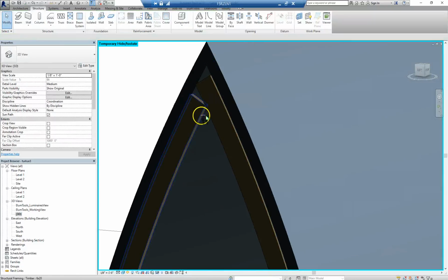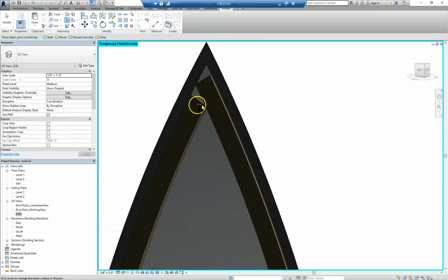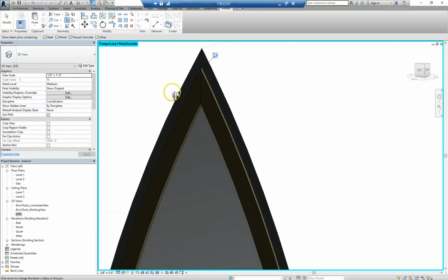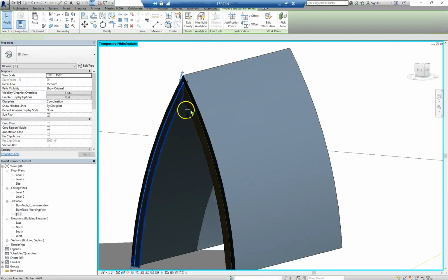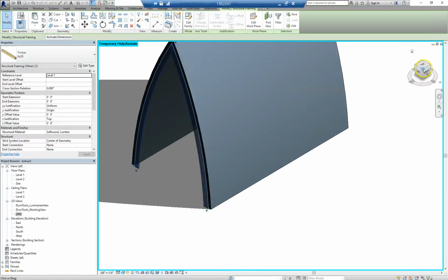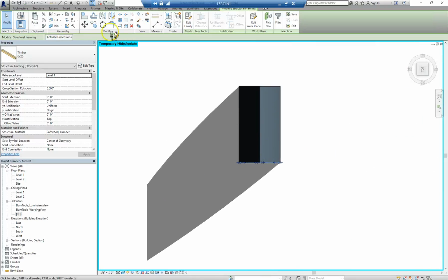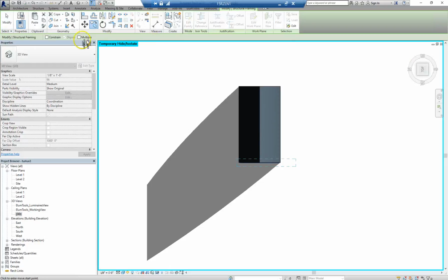Now they're not joining nice, so what I'm going to do is go to the beam join command. No, one up, go up one. There you go. And miter them together. And now once they're mitered, I copy them. You just go kind of to a top view. And I remember when I met with you guys, you said they're about 8 feet apart, so I'm just going with that. I say multiple copies and go 8 feet.